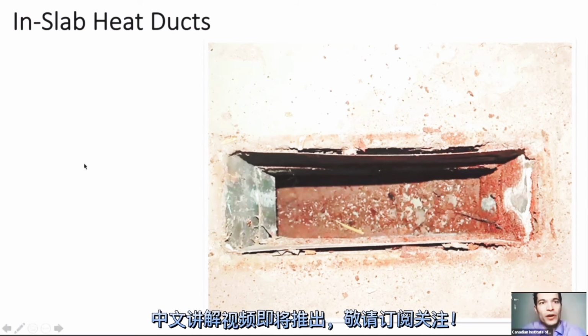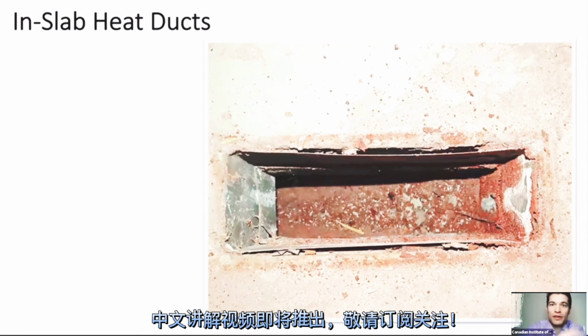Yeah, if you guys come across these in-slab heat ducts, be sure, if you can, to actually pull up the register and look down, because like Sam said, if you see any standing water, any corrosion, any debris, you definitely want to point it out, because usually there's no point in repairing the systems. Usually they'll just terminate it, fill in the ducts, and have a typical conventional system where it runs through the ceiling.